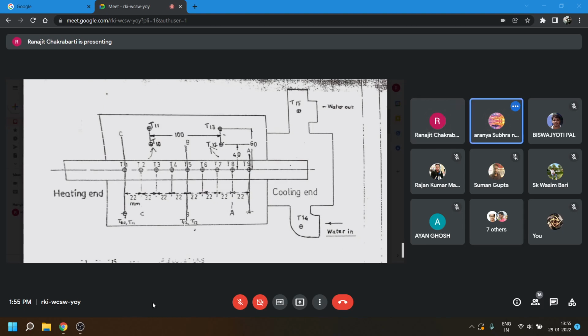Yes sir, it can be seen. Here the heat transfer through this section, on the right side, Q dot BB per unit time, is equal to minus K at this location, that is at section BB, into area at section BB into dT dx at section BB. Now how do I get this dT dx? On the T versus x curve I drew earlier, I took two points, one just before and one just after the BB section, and found dT and dx between those two points. dT dx is negative, so I get dT dx from the curve.